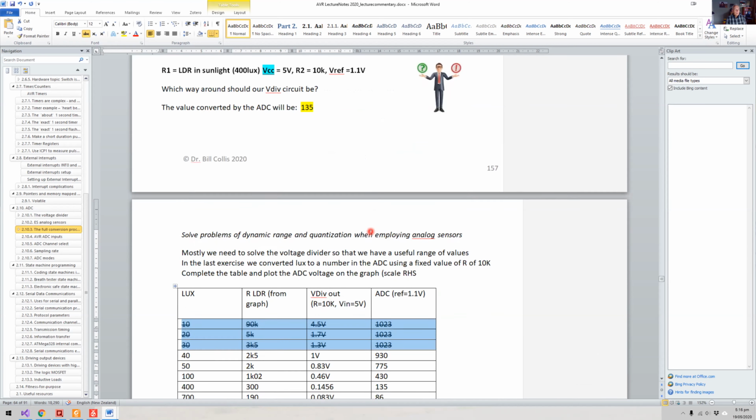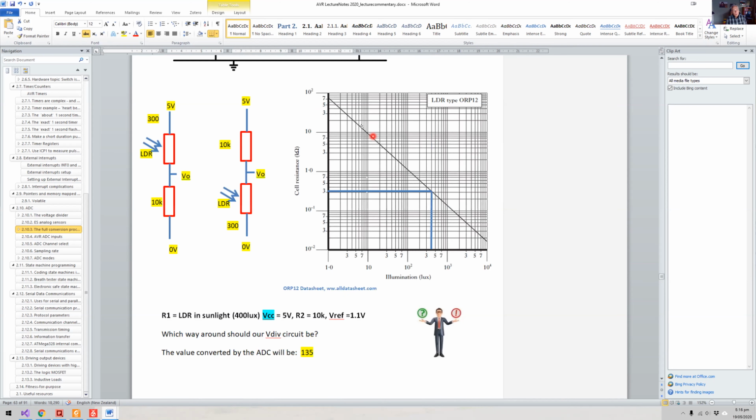So that's quite good. Now, I want you to think also about the fact that we've got a log-log graph here, and our Atmel microcontrollers don't work in decimals particularly well. We have to turn everything into doubles, which is really a float in a normal PC, because it's only 4 bytes of data, not 8 as you would expect in a PC, which gives us probably about 6 digits of decimal points when we're working with floats. Probably quite satisfactory. Of course, it's pretty hungry on calculations.